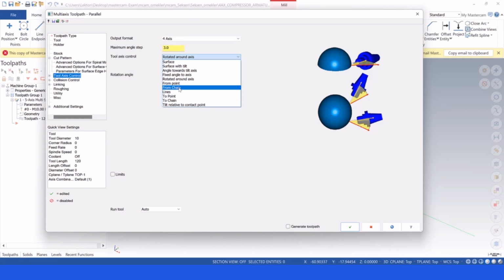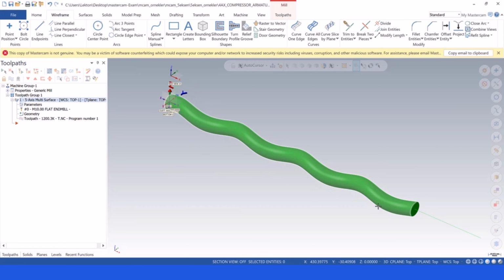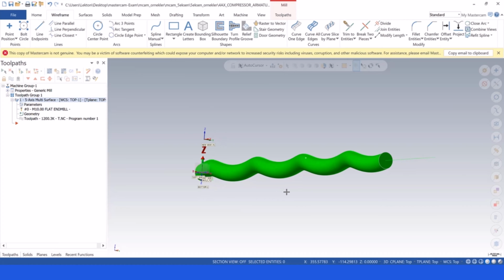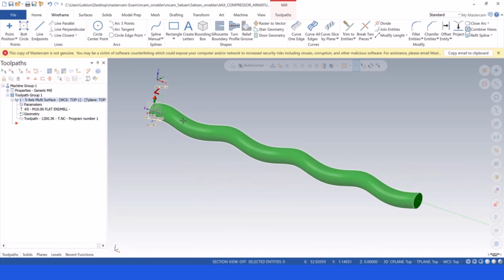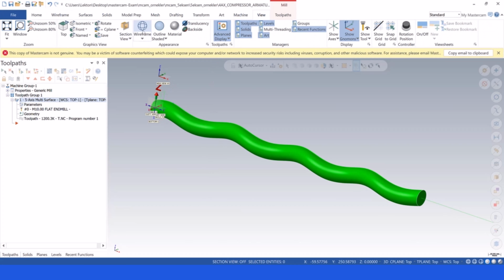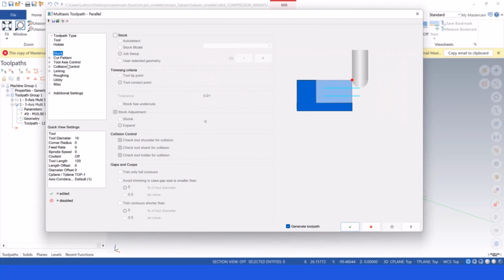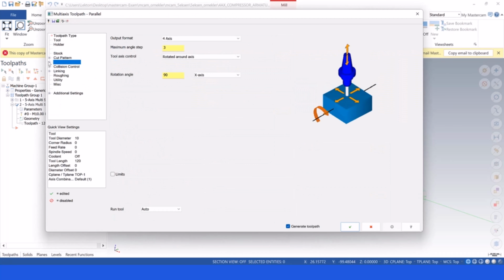For example, it's also possible to create a line on the center of that cylinder. Maybe we have wireframe here. Yeah, that chain can also be selected. Okay, let me check that. I can copy that toolpath and paste it here. Okay, I can turn to parameters. And in tool axis control, I can turn back here, and then I can click from.